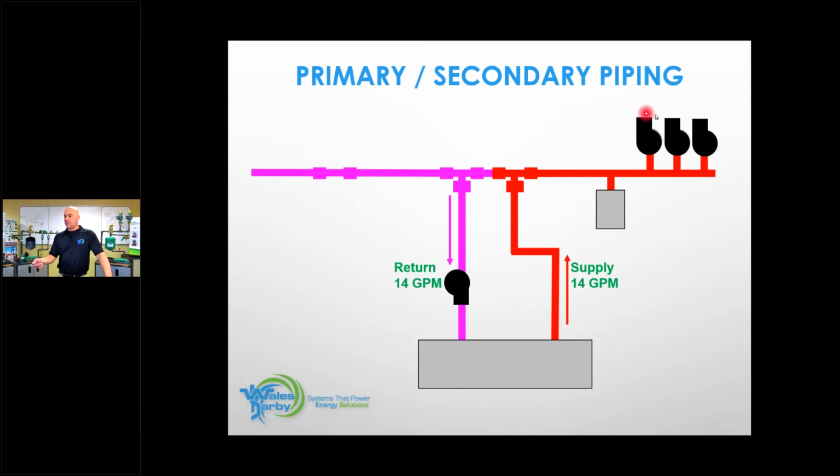All 3 heat circuits are on. If this was your house, you were paying for the gas that's going to be burned by this boiler. Coldest day of the year, what would you like to be going on between the 2 closest spaced T's right now? Live, right now, coldest day, design temperature outside, you're trying to keep it 70 in your house, you're paying for the gas going into that unit. What would you like to have happen between those 2 closest spaced T's right now?